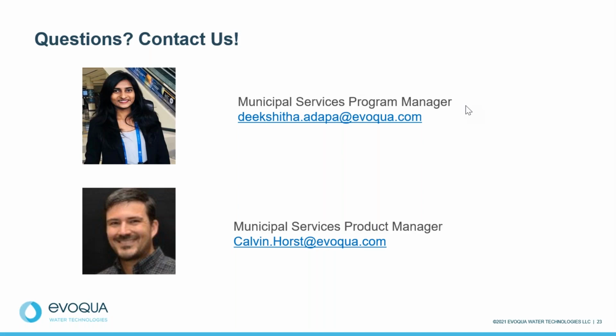So if you imagine our friends in the north, we're here in Florida, we don't have to deal with it, but our friends in the north, when it gets cold, it's not a good thing to have the tanks freezing or product salting out. So we would advocate the use of the double salt solution in those areas. Do recognize that ammonia discharge limits are increasing, and that's an ever increasing concern. So we do have the option of heat tracing tanks and stuff like that if the use of the double salt solution is not going to work for a particular site or customer.